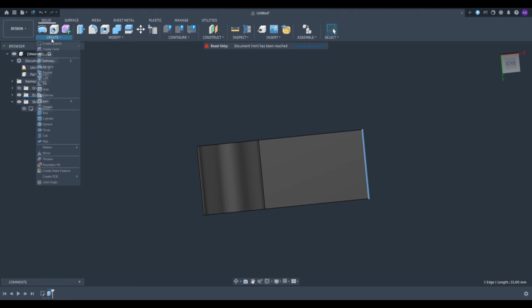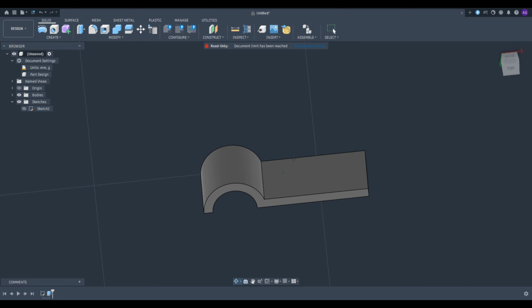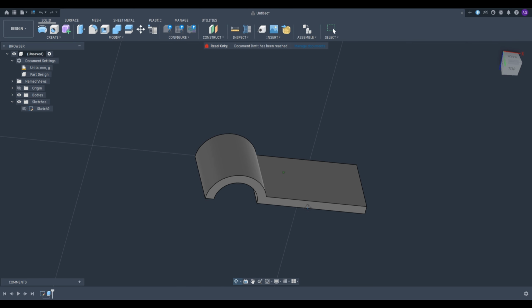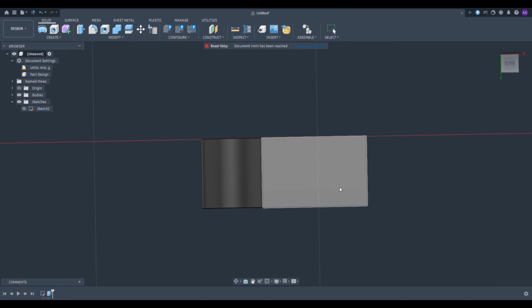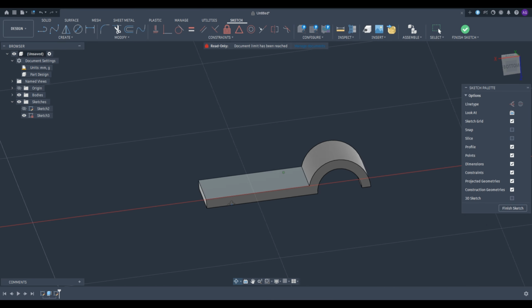We will go to create sketch again, and then we will highlight the face where we want to put the hole. As I'm moving my mouse around, faces will light up, and that's the face you're selecting to be your sketch. In this case, we want the hole through this face, going right through it. So I will select this face. There's a highlight now of the new sketch, and the new sketch appeared over here, while the other one is off. So let me just orient it like this.